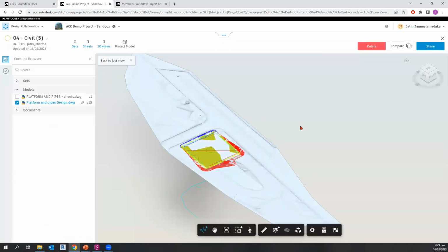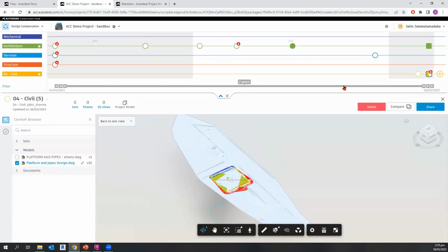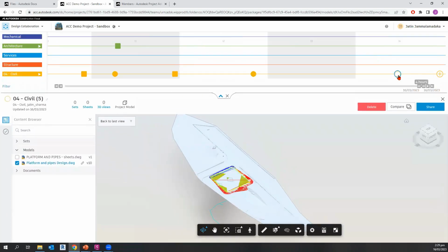And when you hit the save button, you've created what we call a package. Okay, so if we look at our timeline symbol, we can see over here a little circle that says, yep, a package that got created. Now at this point, this is a common support issue that we get, because we get a lot of clients that say, hey, I've created a package, but no one else can see it, and no one else can do anything with it. So it's not until you hit the share button that it becomes available for all the other teams to take a look at. Until then, it's only your file.